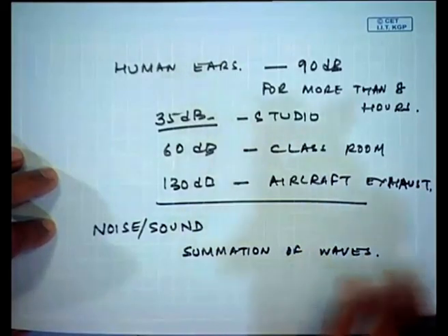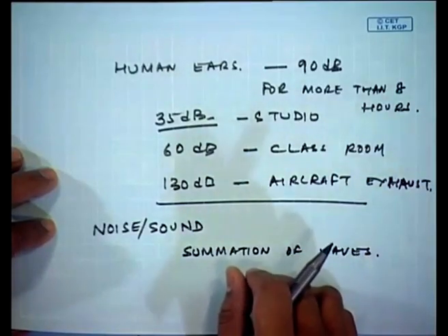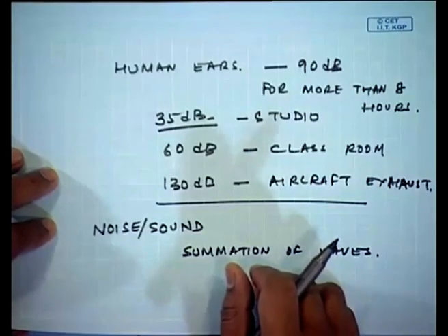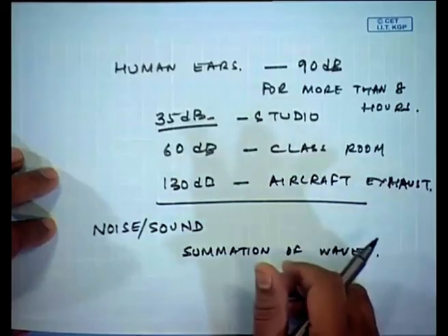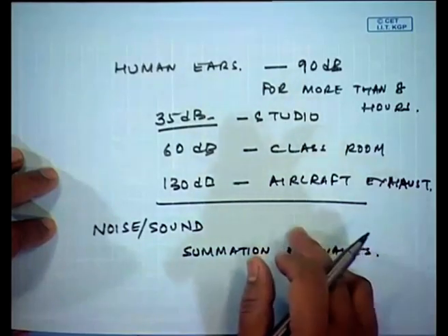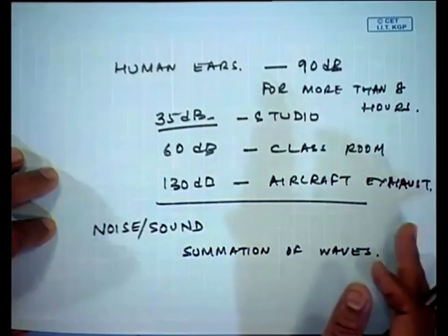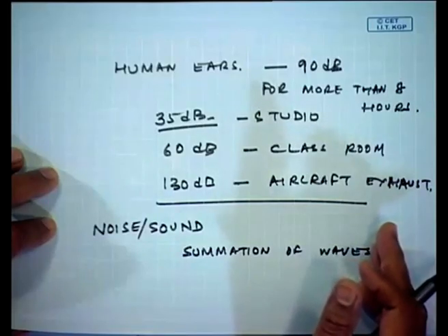For example, if I was to monitor the sound radiated by a machine, do I need to have another machine next to it running or no? Obviously, your answer would be everything else should be quiet. We should be only running the machine whose noise is to be measured.